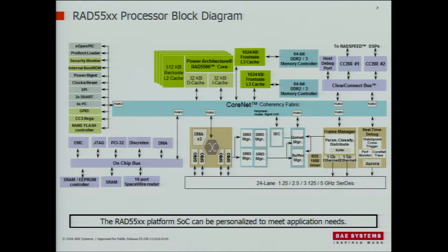So you can use these PAMUs to prevent a DMA controller from stomping on some random area of memory because you set it up wrong. It can do address translation for you. It has a lot of function. It has this nifty ability such that you can create domains within your system and actually partition hardware so that you have these walls between different domains in the system. So there's quite a bit of functionality there.